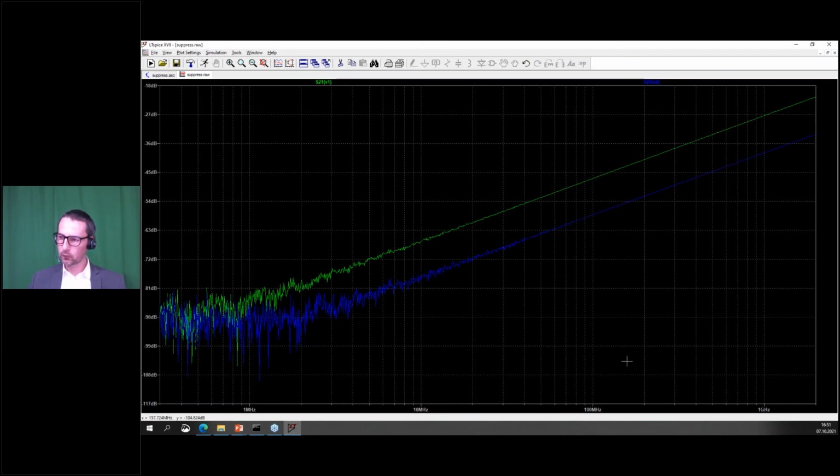I would love to have a little bit more still, because finally I want to safely transfer signals like USB and really make it work, and not have to tremble and think about whether it's working the whole time. So that is where layout number 3 enters the ring, and that's where we separated the 2 signal pins with 1 row of ground pins.